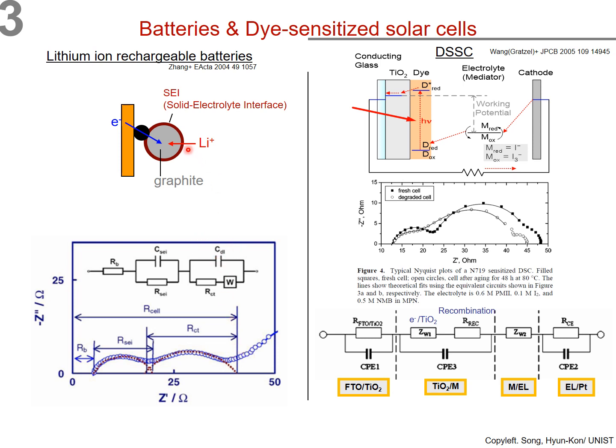Then the lithium ion would travel inside of the graphite. This is a kind of diffusion, more accurately solid diffusion, so we should have Warburg impedance here. So the equivalent circuit model is the Randles circuit. By using those three parts, we could describe the system of lithium-ion batteries when lithium ion is intercalated into graphite. That is the first example.